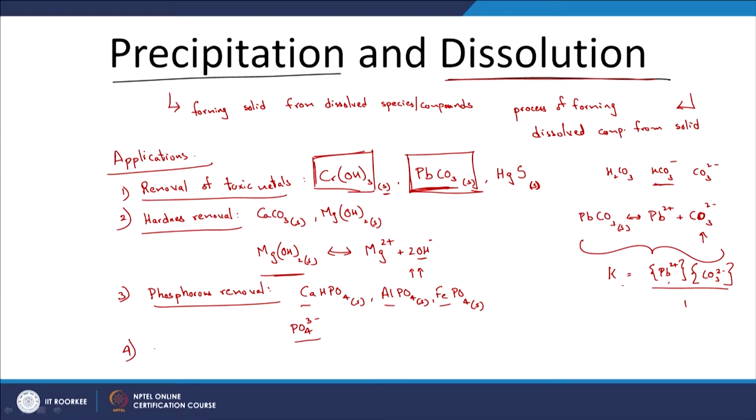Again, this is obviously linked to your aqueous complex based chemical process, and the next logical step would be your precipitation. The next aspect we are going to move on to is iron and manganese removal. In this case we can remove ferric in the form of Fe(OH)3, and manganese as MnO2, and thus the applications of Fe(OH)3 precipitating out are remarkable.